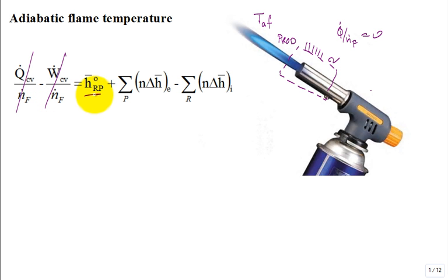We have whatever is the fuel, and it has a different heating value or a different enthalpy of combustion. We bring in all our reactants typically at 25 degrees C, not hot or cold, just at standard conditions. Then we can compare apples to apples. Does your fuel burn hotter than this other fuel or not? And this right here is where you have the adiabatic flame temperature.